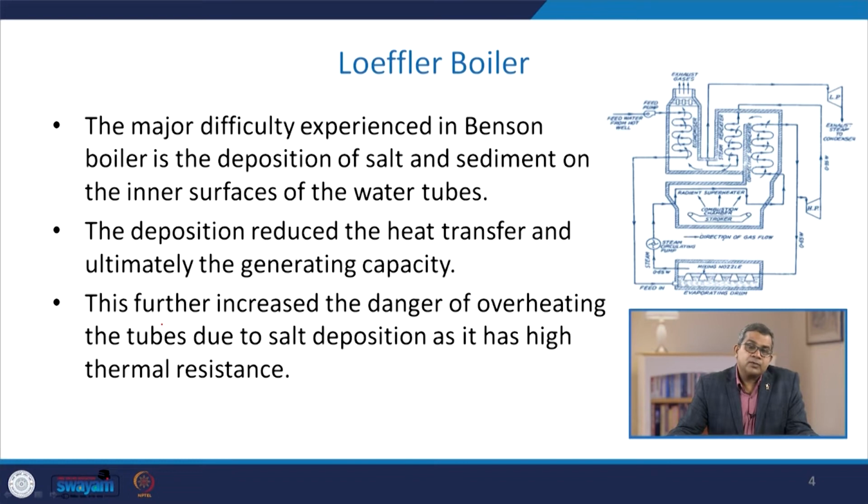When we were discussing the concept and basic anatomy of the Benson boiler, there are certain difficulties or disadvantages associated with it, although it is a high pressure boiler. The major difficulty which people experienced in the Benson boiler is the deposition of salt and sedimentation on the inner surface of the water tubes.